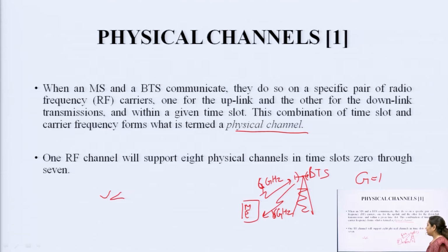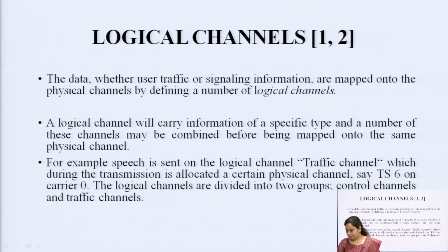Now, one RF channel will support 8 physical channels in time slot 0 through 7. So, 0 to 7, different channels are going to communicate within a single RF channel. Now, next is logical channel.